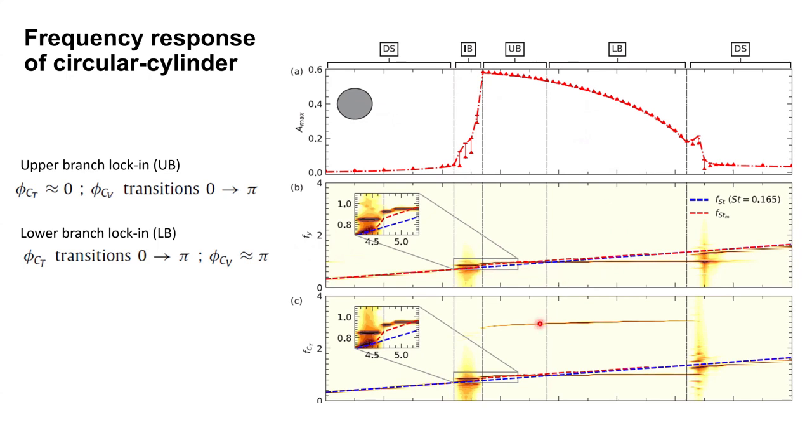And in the vortex shedding frequency, you can see there is a third harmonic present because this is around 3, and this also appears in the signal, and that has been explained by the fact that we have symmetric vortex shedding. So after the lock-in region, the cylinder desyncs and its frequency is close again to the Strouhal frequency, as you can see here. So in a way, the frequency of vortex shedding gets modified and it locks in to the cylinder natural frequency, and the amplitude is larger. So this is roughly the idea for a circular cylinder.